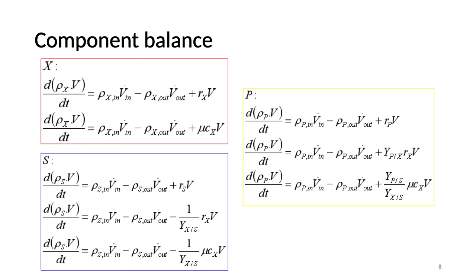Next, I am applying mass balance for the substrate S. The rate of generation of substrate is Rs, but actually substrate is not generating, it is consumed. If we only consider the cell growth by substrate, we can put Rs as a function of cell mass yield coefficient and growth rate of cells. But in reality, Rs is estimated based on cell growth, product formation, and cell maintenance. But I am not going to explain it further at this point.